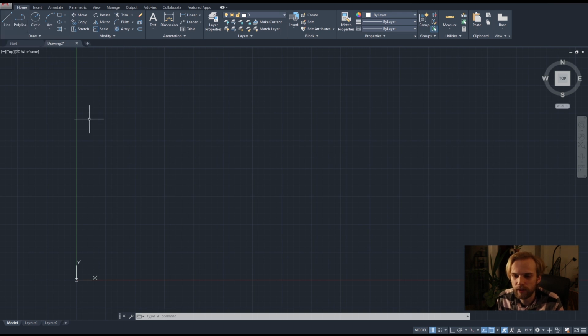The line tool is the most simplistic tool, and all it can do is straight line segments that are, so to say, exploded. They are separated line segments, right? The polyline tool, on the other hand, can contain much more information inside of it. What I mean by that is, first of all, let's learn the shortcut for it. The shortcut is PL, enter, or clicking the icon, of course, but PL, enter, gives you the polyline tool.